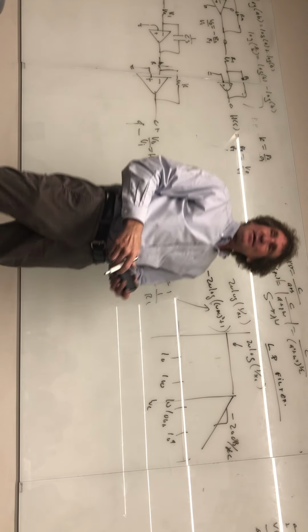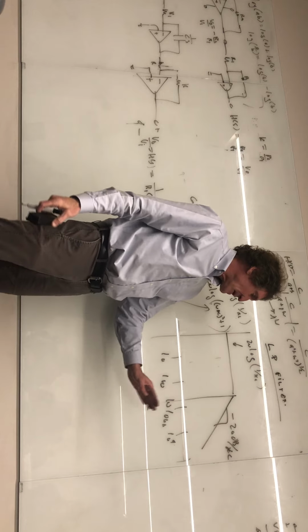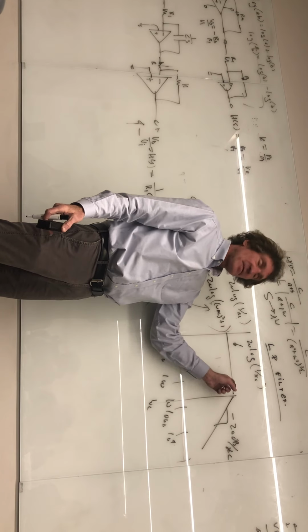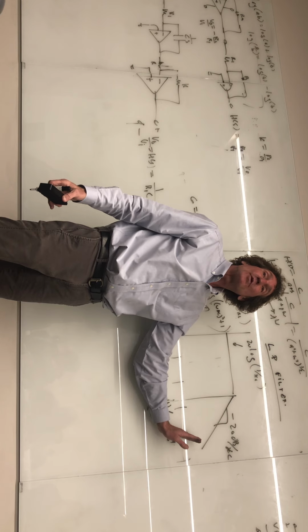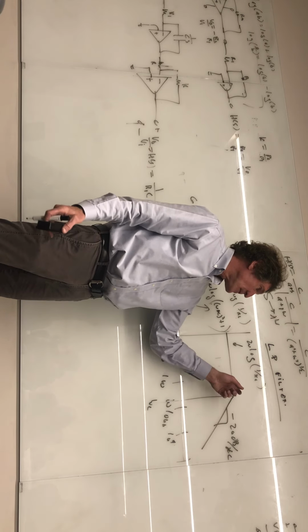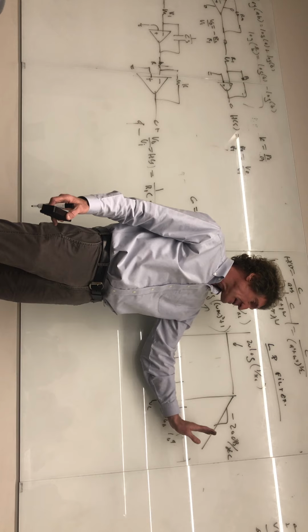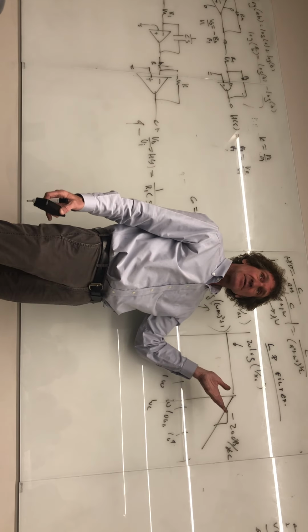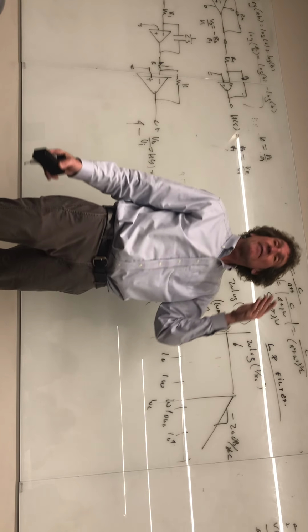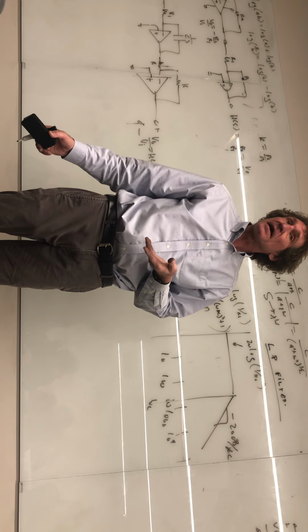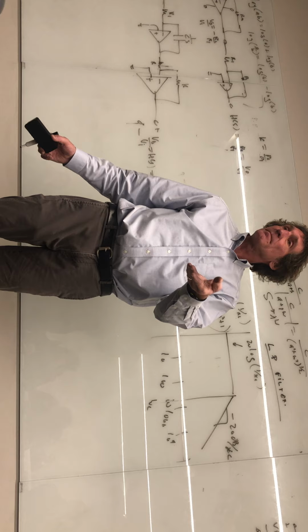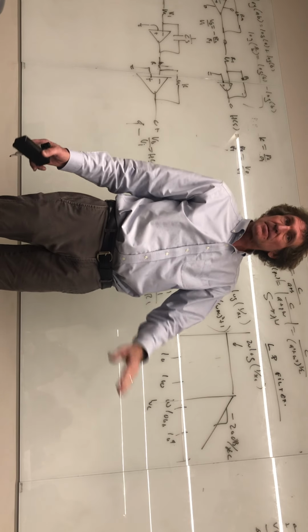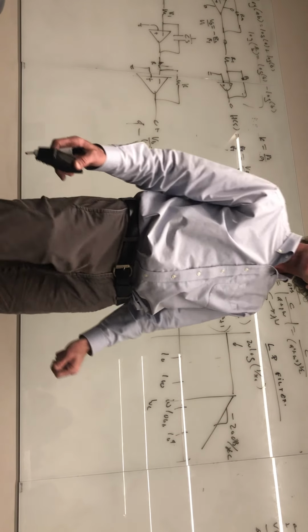Now, what does 20 dB per decade mean? If I'm at 1,000 and I have a value of 10, a decade is 10. At 10,000, I would have 20 dB less. So if you had 40 dB here at 10, and you want 1 decade, and it's minus 20 dB per decade, you would have 20 dB left. Follow me? Another decade up, you would have 0 dB. Understand, everybody? That's 20 dB per decade roll off for a low pass filter. That's a very common filter.